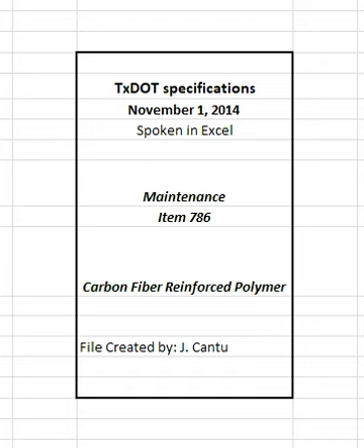2. Materials. Provide unidirectional high-strength carbon fiber fabric, fully saturated with compatible epoxy resin per manufacturer's recommendations, to form a CFRP system unless otherwise shown on the plans. Use carbon fibers in the CFRP system that conform to the minimum requirements of Table 1 and are pre-approved for use unless otherwise shown on the plans. Pre-approved CFRP systems are listed on the website maintained by the department, or shown on the plans.